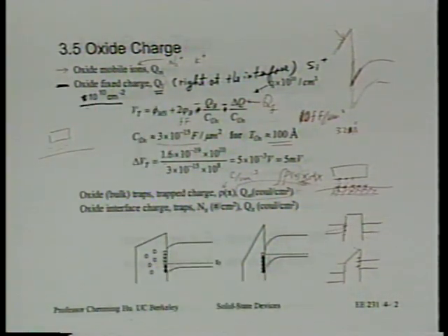The way you do that is you deliberately heat this capacitor on a hot plate and apply voltage to it, to see if the threshold voltage or flat band voltage or the CV curve moves back and forth as a result of applying voltage across this capacitor. All right? If you see that happen, if the CV is not stable under temperature bias, then you know there is a mobile charge in the MOS system.